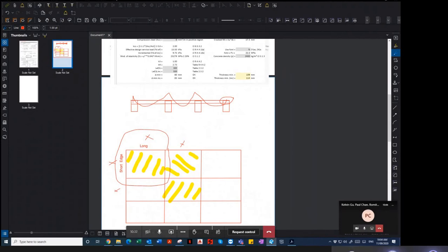So that's how, because it's one piece, and being an in situ construction, it's monolithic, so it's one construction. So there is some moment transfer, but a lot of the moment is transferred over here at the supports, and that's what's helping the beam or the slab to work and be more efficient, because it transfers the moments from here to there and goes down across and so forth.